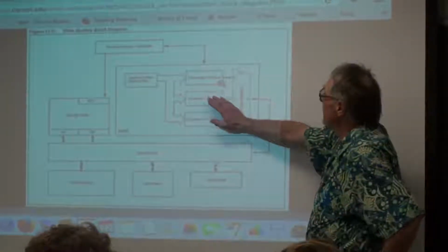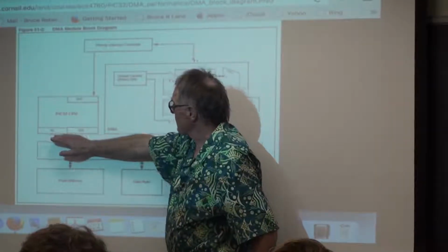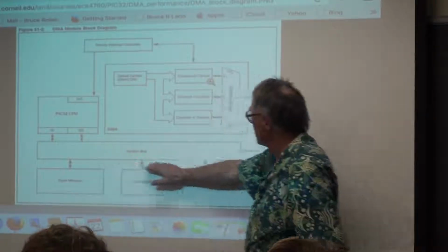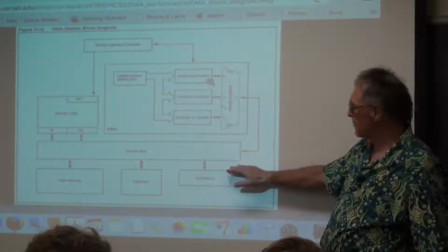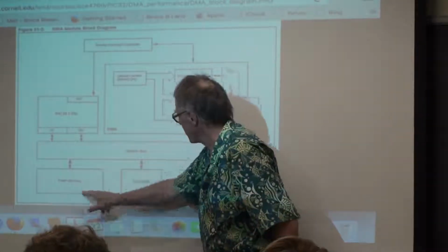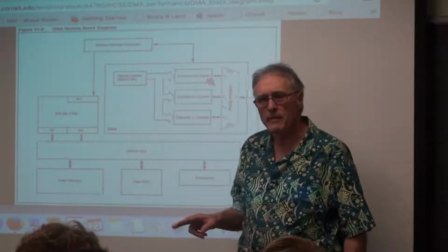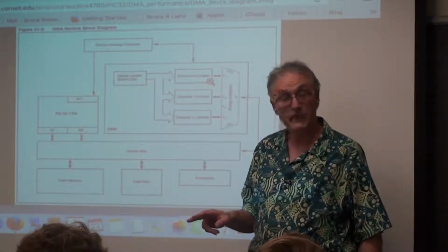In terms of the layout, you have an instruction generator, address generator, and a data address generator that can read the system bus. This is not a bus exactly, it's actually a switch matrix, and it can read flash, data, or peripheral. Does that mean you can execute code from RAM? Yes, in fact you can.